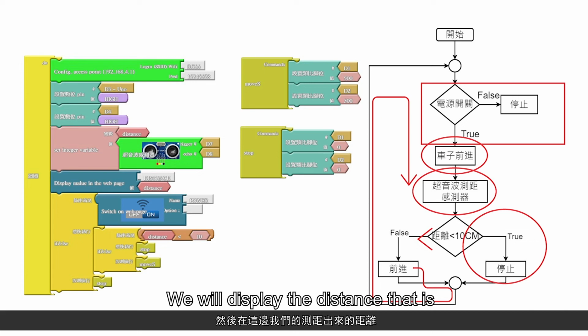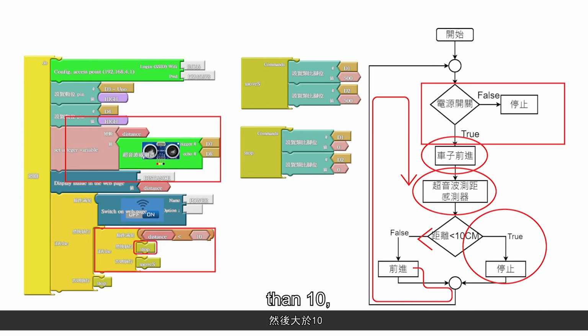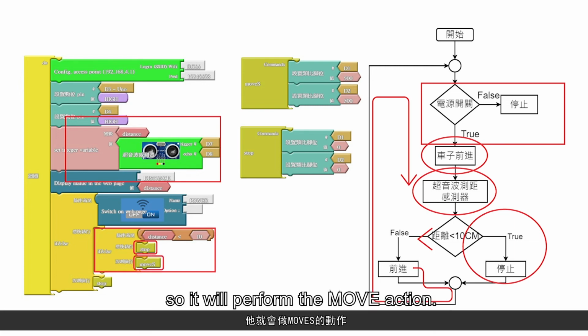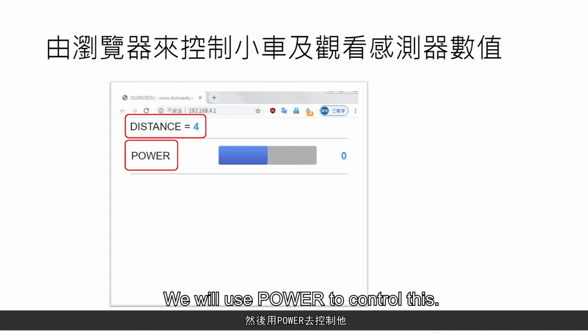We'll display the distance that is being measured, which will be evaluated here. When it's less than 10, and it's true, then it will stop. If it's greater than 10, it means that the obstacle is still far away, so it will perform the move action. Let's practice this part a bit. Later, we will have the measurement result displayed here. We'll use power to control this.